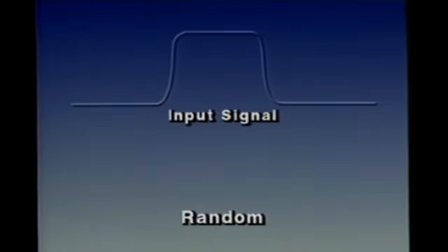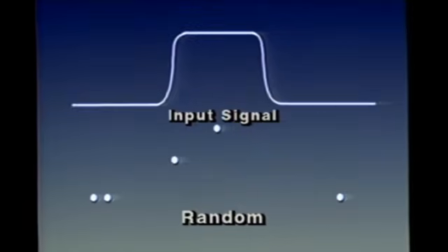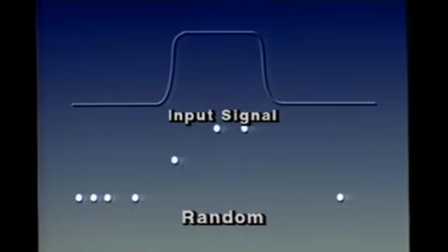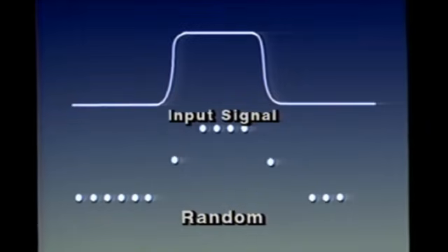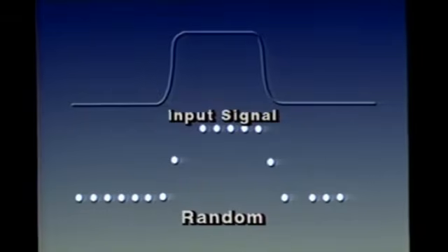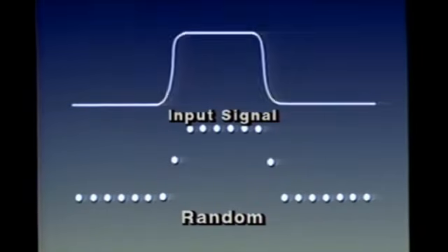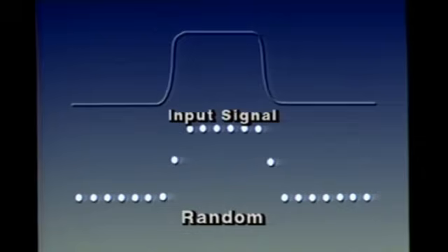Random equivalent time sampling acquires sample points in a random sequence relative to the trigger point. In this simplified view, only one sample point is taken per input cycle. But many DSOs actually take more than 1 point per input cycle to speed up acquisition time.